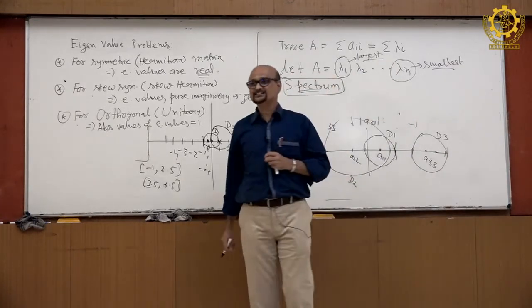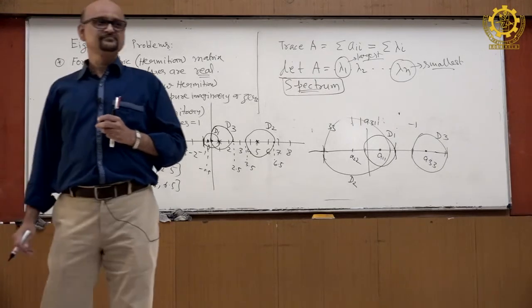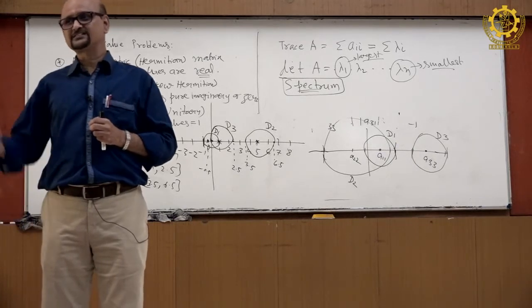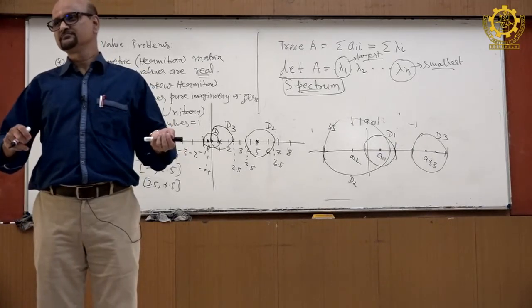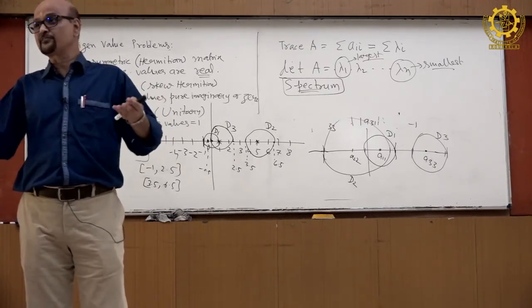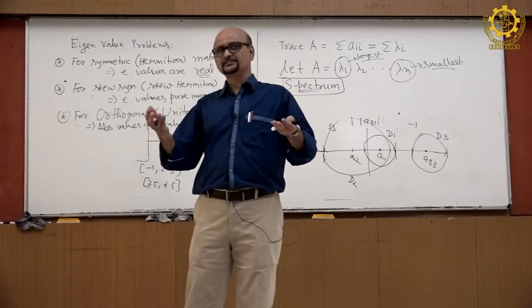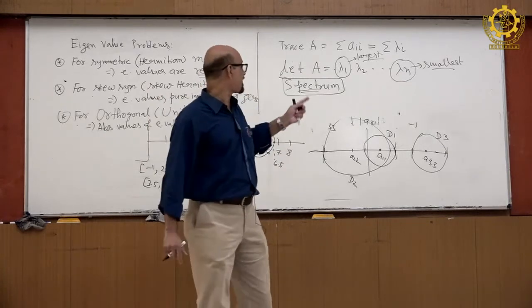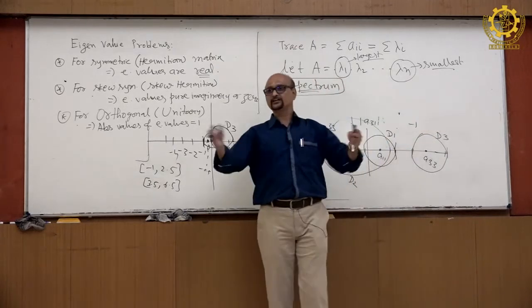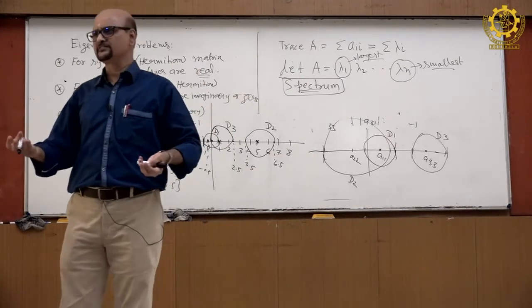Now, if I know the largest and smallest, can I safely design? The largest frequency and smallest frequency should not be crossed. Lower bound and upper bound I need mainly for practical purposes. For other purposes also they are needed. In general, you have now understood that I need only the largest eigenvalue and smallest eigenvalue, as all eigenvalues are inside that bound. If I know these two, practically it is done.